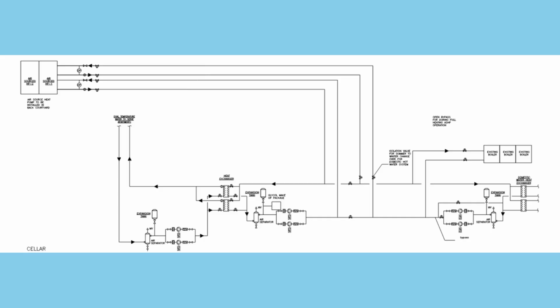It is not as simple as issuing a BMS command to switch from cooling to heating or vice versa. A proper changeover requires a clear understanding of the system and careful management of the loop temperature to bring it within the compressor's operating envelope for the selected mode. It is important to review the mode changeover procedure with the heat pump manufacturer's representative, obtain their approval, and, if possible, document the process in writing for future reference.